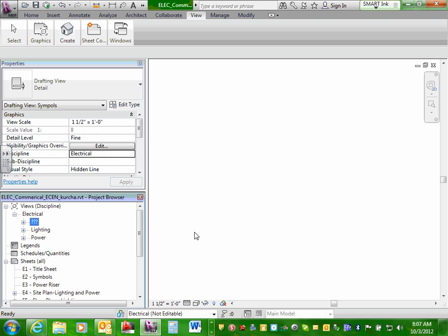Okay, now you have this. Cool. Now here's where I want you guys to wake up. Every drafting view, every time you want to bring something from CAD, what do you need to do? Drafting view, name it, change the discipline to electrical, and it will be listed right in here.